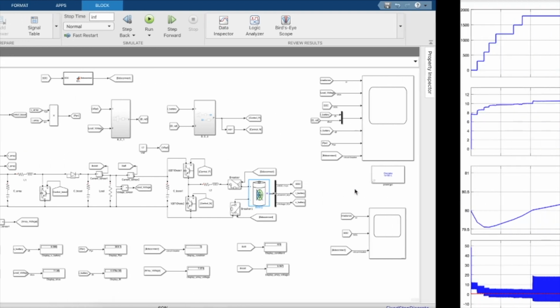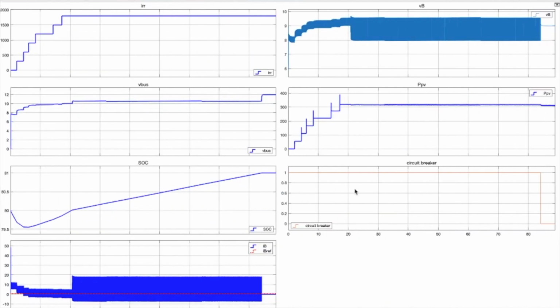So let's look at a sample result that we did run. This particular simulation takes a long time to run, and it takes about 1 to 2 hours to charge up to like 10 to 15% of the battery. As you saw, our battery input is dependent on the irradiance. When the irradiance was initially 0, our initial state of charge of the battery was 80. So it started to drop from 80 and started to discharge the battery because there was no power generated by the solar panels.